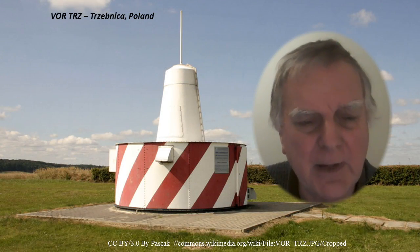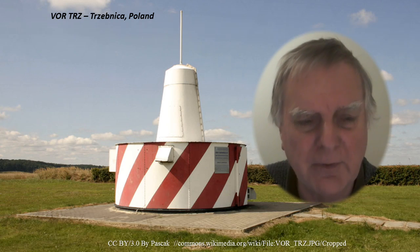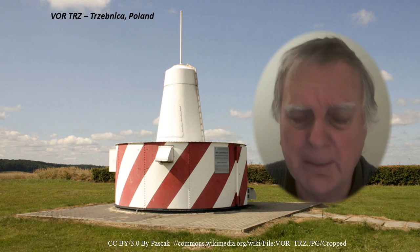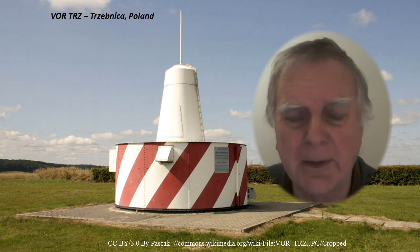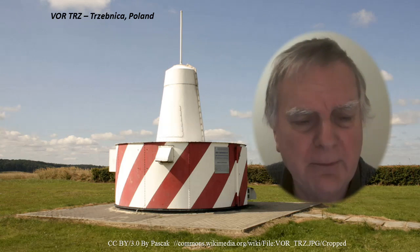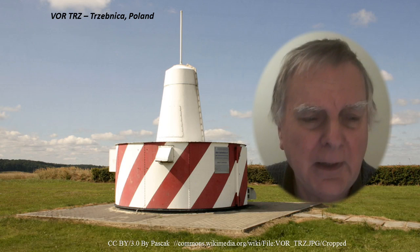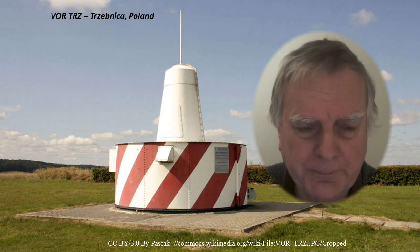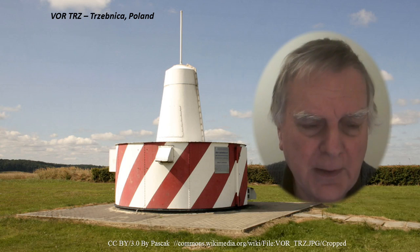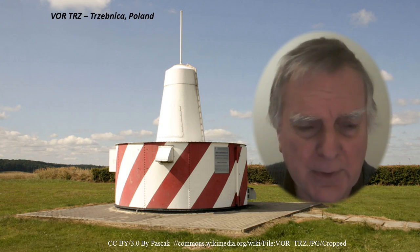VORs have adapted over time. The conventional VOR started out with an electromechanical system involving a spinning dipole, later converting to an all-electronic implementation, as we talked about earlier. But the big improvement was the widespread adoption of the Doppler VOR, which significantly reduced the effects of multipath propagation. However, this came at a considerable cost penalty, with the need to provide a bigger site, many more antennas, bigger counterpoise and so on.